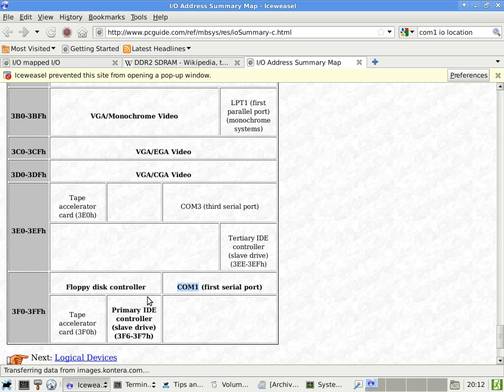Another location may specify, okay, how many data bits do we have? How many stop bits do we have? How many parity bits do we have? So all of these things that you normally have to specify when you want to talk to a modem back in the good old days, they all have to have corresponding byte locations in I/O space. So every time you want to change the baud rate to talk to a modem, you have to change one of these locations accordingly. And that's how your computer, that's how your processor can talk to the I/O devices,